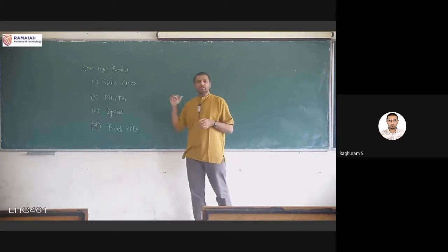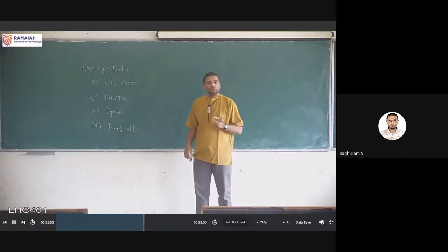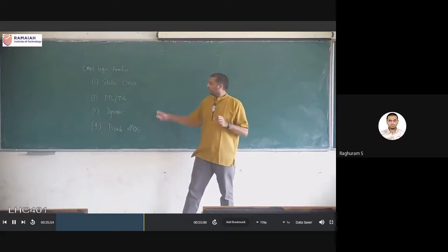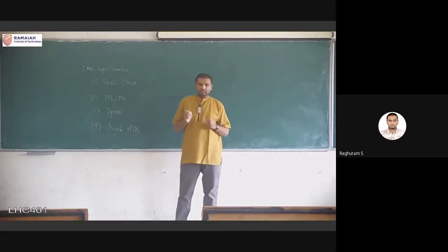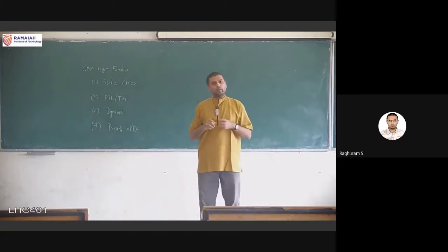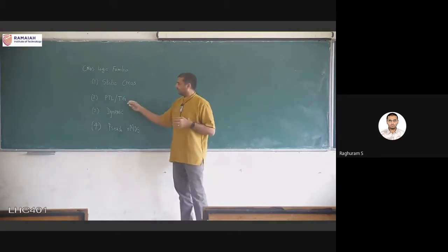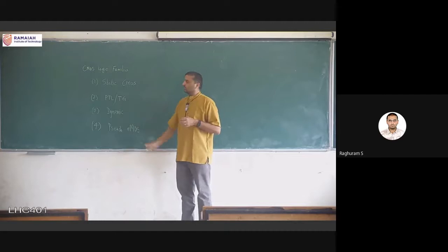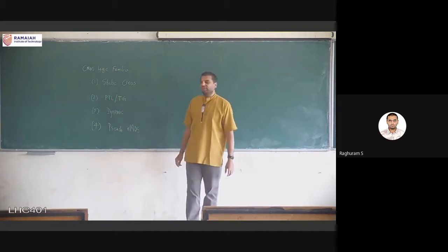What we have been doing so far, that is pull-up network, pull-down network, dual, structural dual, etc. In particular, that is called as static CMOS logic design. That is the most common and by far it is the most popular also. And there are other options, and we are going to see the next one, which is using a different type of functionality of the transistor. It is called as pass transistor logic or transmission gates. They are both somewhat similar to each other.